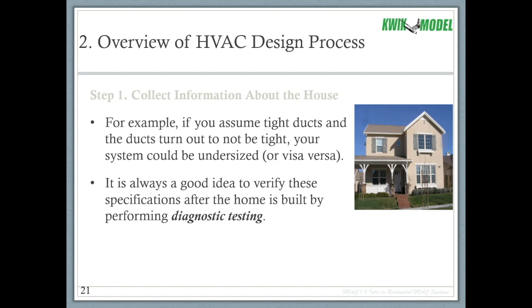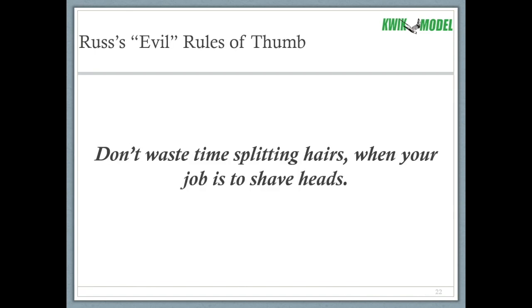Okay, infiltration can be one of the largest single sources of load, especially on the heating side, and so it's very important that you know that as best as you can. Another rule of thumb, don't waste time splitting hairs when your job is to shave heads.